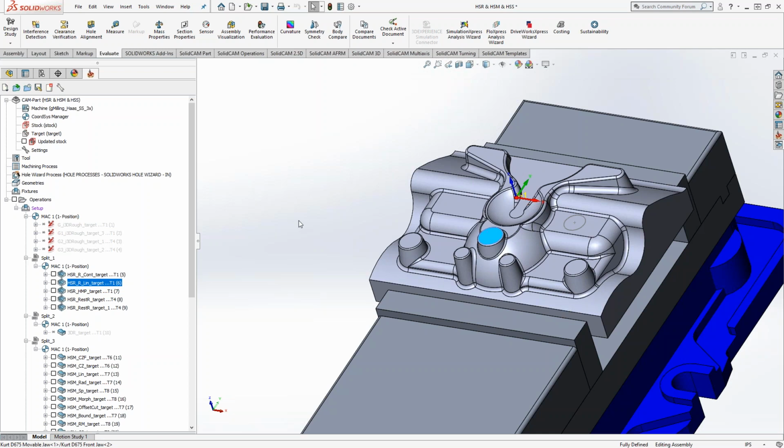With iMachining, you'll have that smooth consistency. That scallop is always going to be the same height throughout the entire part, whereas on constant stepover, your scallop may be much smaller on a more horizontal surface. So you're going to get scallop heights that are constantly varying, which will lead to different finish results when you finish that part off.